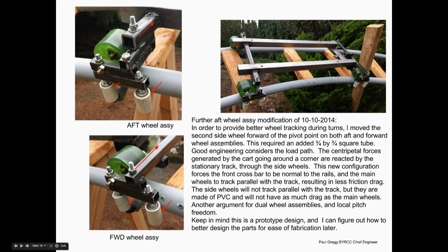I did have some trouble keeping these things stable. When I do design work, what you really want to be thinking about is what the load path is. So there was a lot of going out and putting this on the track and pushing out on it, simulating the centripetal force that would be on it, the overturning roll moment and stuff, and pushing on it to see how these things were working. And you can kind of visualize what the loads are. This is a load. The cart's trying to go that way, and the track is stopping it with these two wheels, and that's how the loads are going through here. So I had to fiddle with just where these pieces were every once in a while.